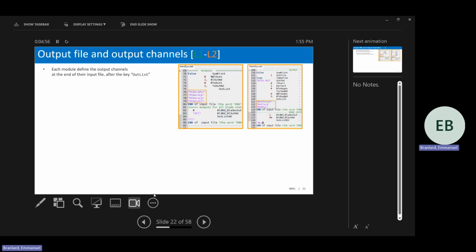Output files, yeah. I mentioned earlier, OpenFAST is going to create a .out file. How do you select what's going to be in this out file, like the rotor speed, the rotor power? I want to know the rotor CP, the power coefficient as a function of time. Those are specified usually at the end of those input files, and each module has different outputs. Again, how do you figure out which module has which outputs is a challenge, but I think we'll cover this.